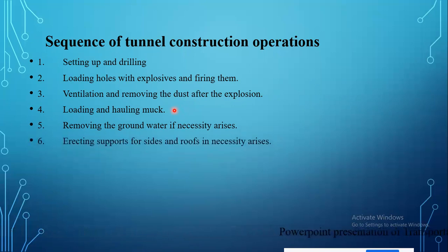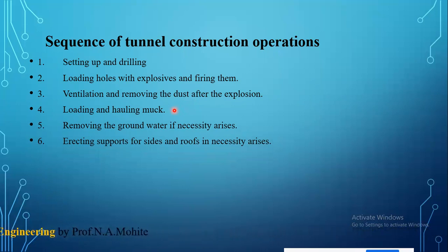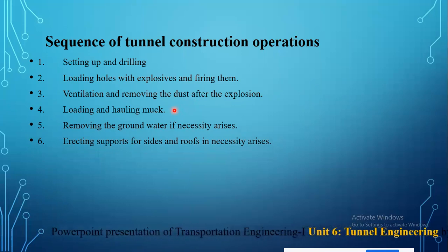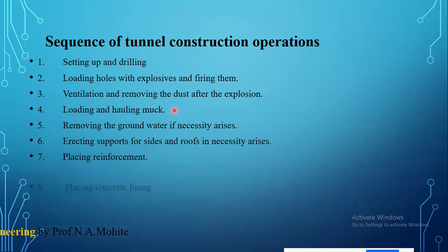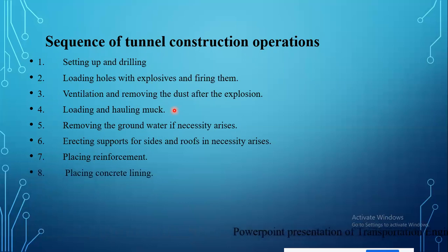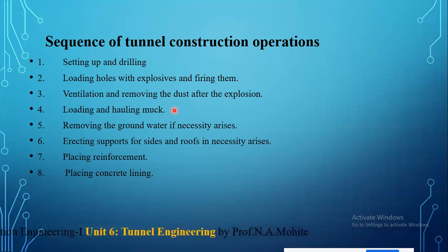Then you are supposed to provide supports for the sides and roofs if necessary, because there are chances of rock falling or settlement of the upper surface. Then you place the reinforcement, and finally the concrete lining is placed, which is the final step.